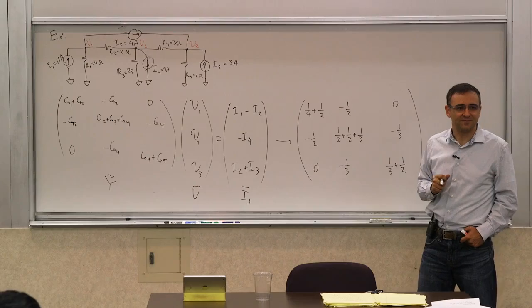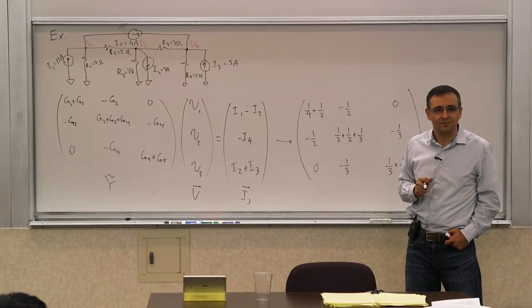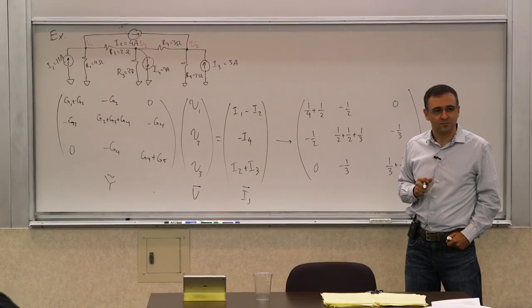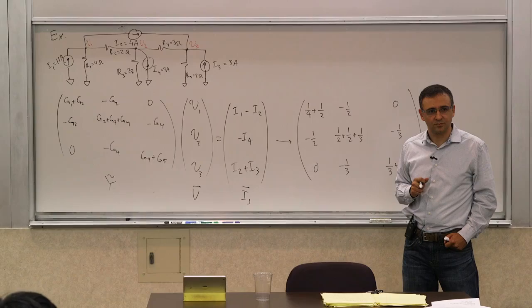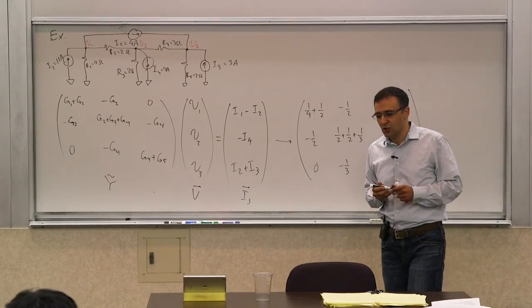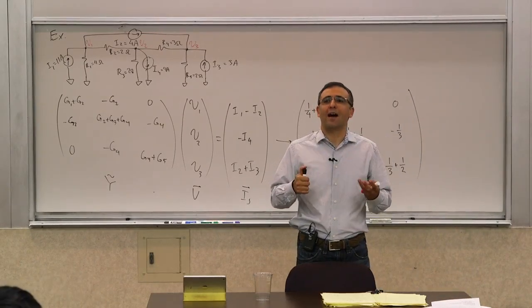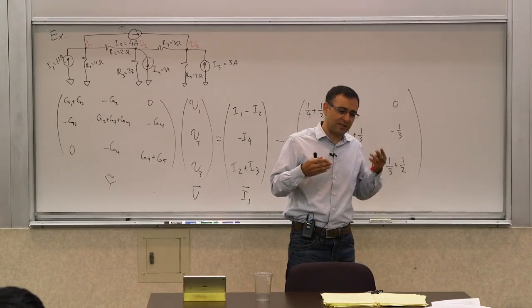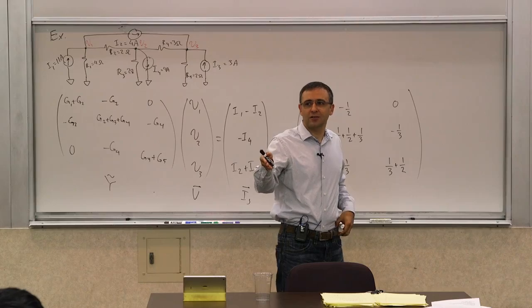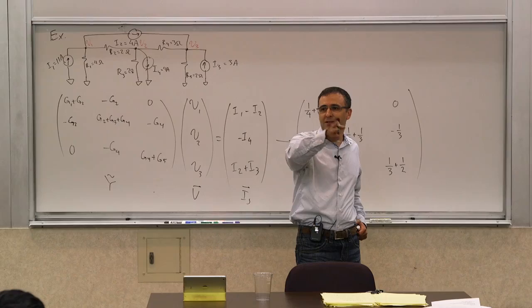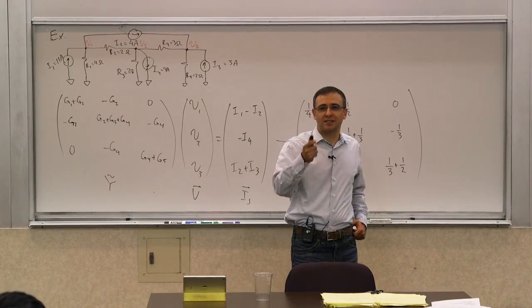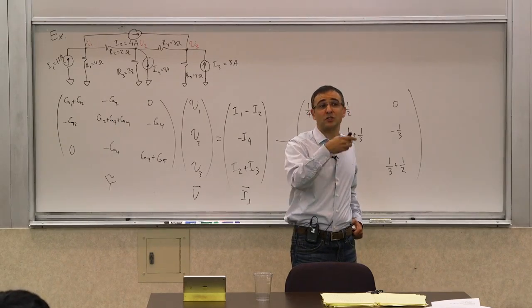Yes? I noticed that in the textbook, about the independent sources or dependent sources, it would say that the current source was proportional to the voltage of something else, and it would just pretend that the units weren't an issue. Right. So your question is about cases where there's a dependent current source that depends on a voltage, or a voltage source that depends on a current, and they ignore the units. It's not a good practice. For those cases, you need to really state it.